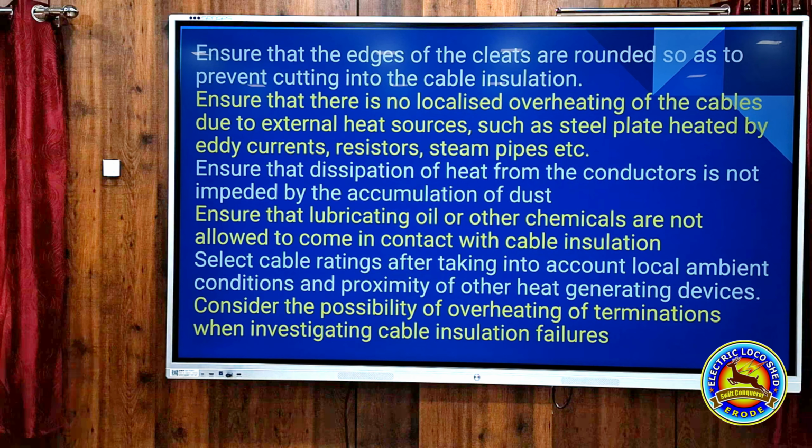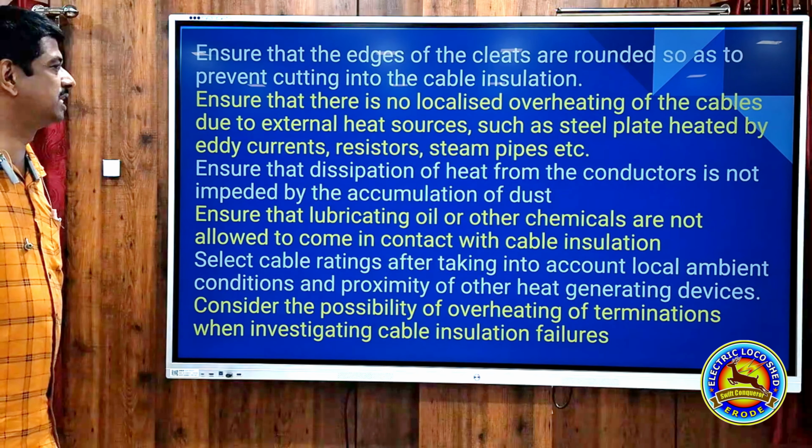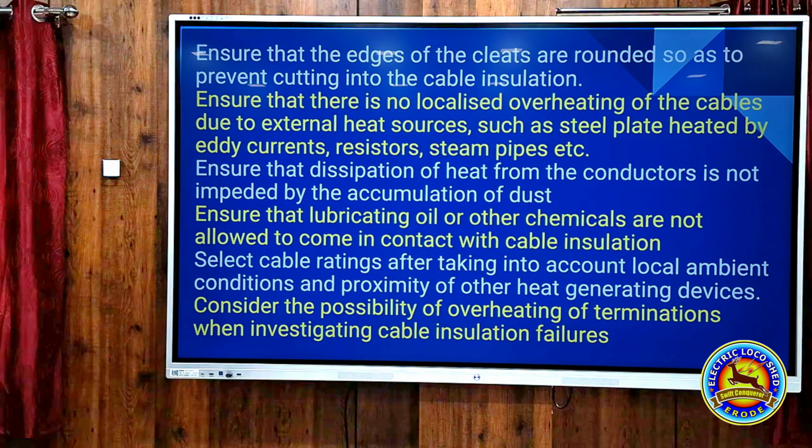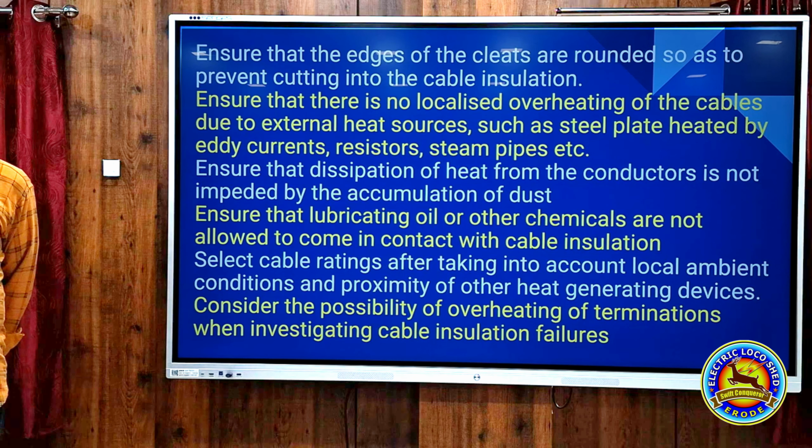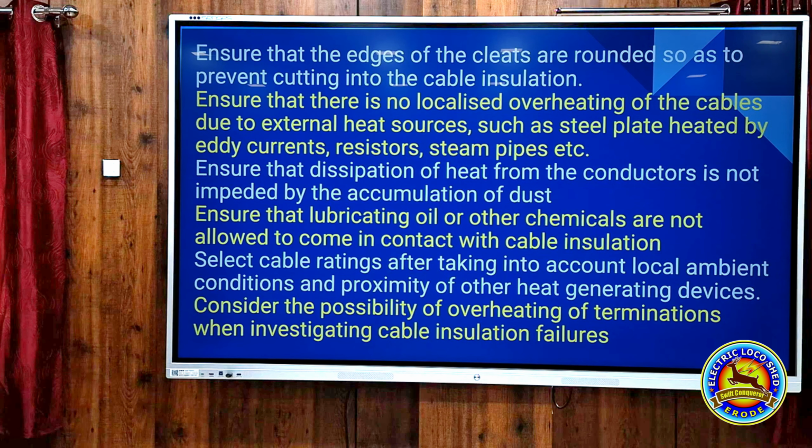Ensure that there is no localized overheating of the cables due to external heat sources such as steel plate heated by eddy currents, resistors, steam pipes, etc. That is, the cable should not get heated due to any external factor.